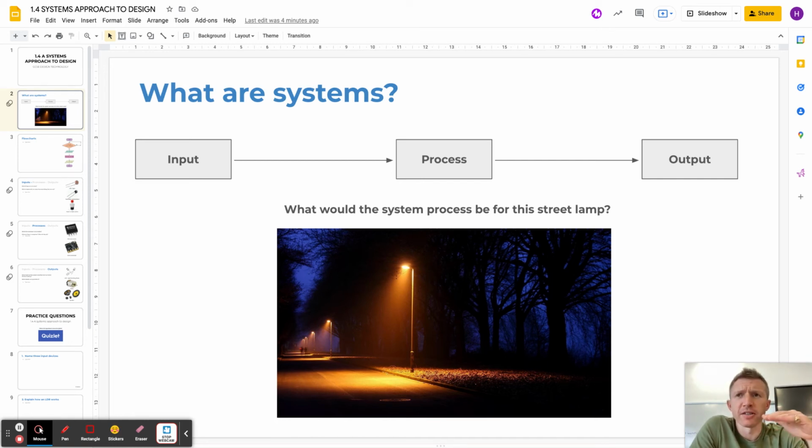Let's say that the light level benchmark is 30 out of 100. 100 is full daylight and 0 is complete darkness. So let's say 30 is the value at which it must turn on the output. It's constantly checking the data it receives from the input, which is sending data the whole time. It'll be gradually going down during the day, and when it gets to, say, 31, and then 30, and then hits 29, it'll think, oh right, it's gone below that benchmark. I now need to tell the output to turn on. Or it doesn't even tell the output to turn on, it turns on the output. So the processor does all of the thinking and all the commanding, essentially.